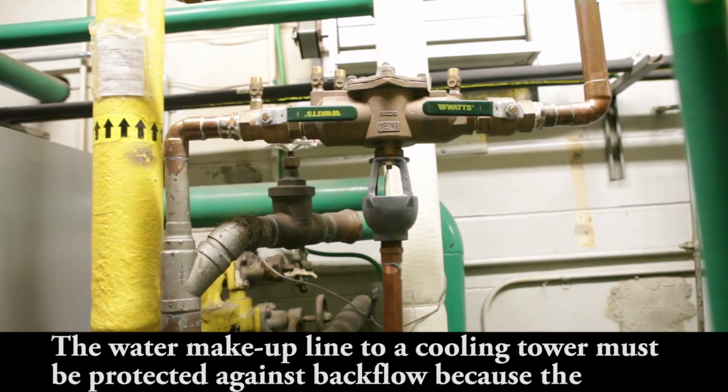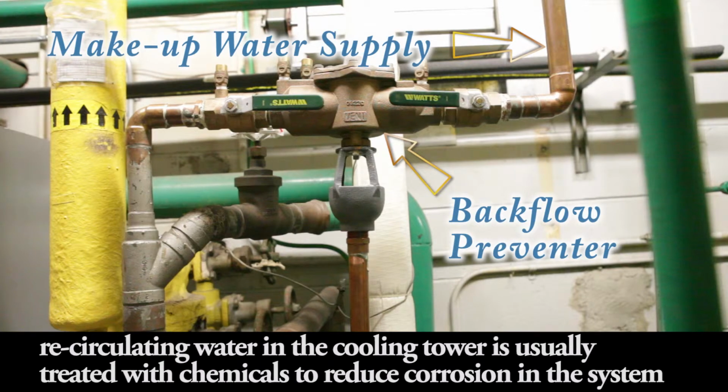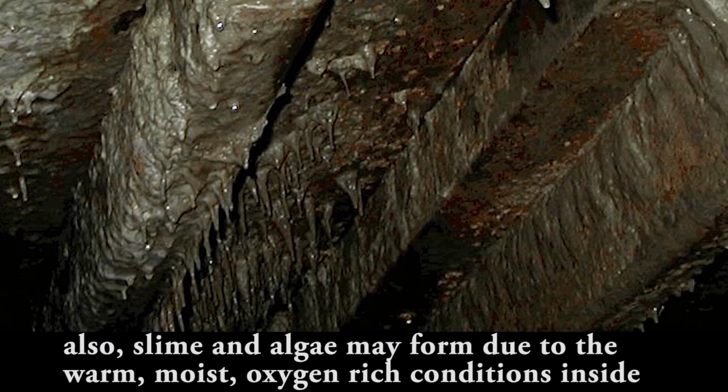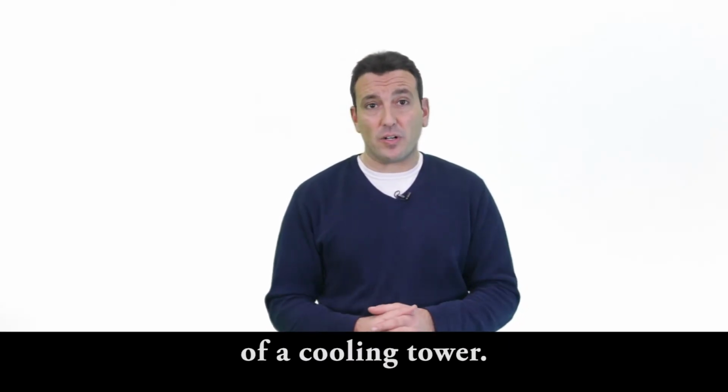The water makeup line to a cooling tower must be protected against backflow because the recirculating water in the cooling tower is usually treated with chemicals to reduce corrosion in the system. Also, slime and algae may form due to the warm, moist, oxygen-rich conditions inside of a cooling tower.